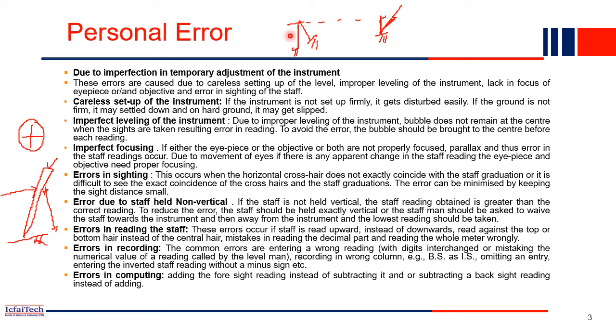So what he has to do is, the surveyor will give some signal so that he will move. Initially it will be in this position, then the surveyor will give a hint so that he will change it. So now he will rotate it forward and backward. The surveyor will take multiple sightings and multiple readings, and which one is the least. Initially, if it is inclined, then this length may be 3 meter. The surveyor got 3 meter. Now he asks the assistant to move the staff forward. Whenever he moves it forward, the reading is reduced and it is now 2.5 meter, for example.